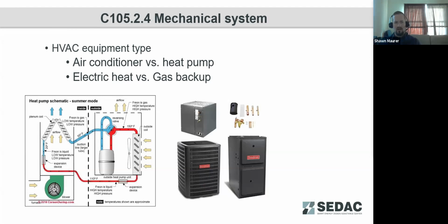One thing to be aware of with air conditioners versus heat pumps: if you do have heat pumps installed in the building, there is that additional commissioning requirement to make sure that the reversing valve is working properly for that heat pump to function as it should.